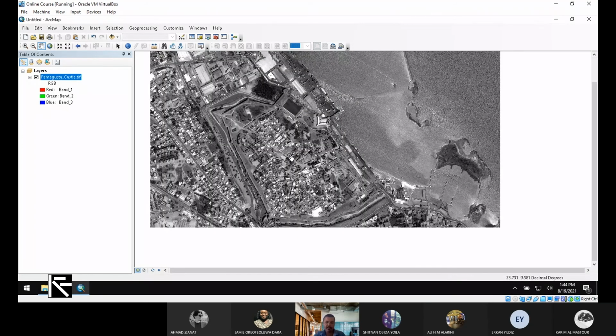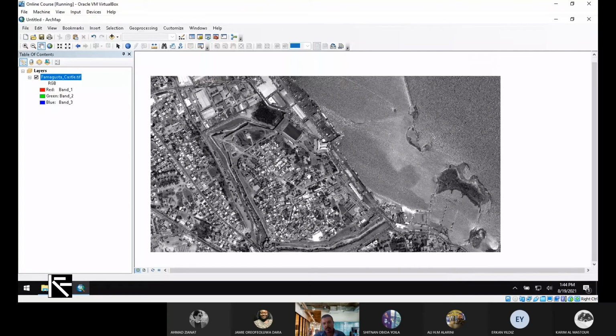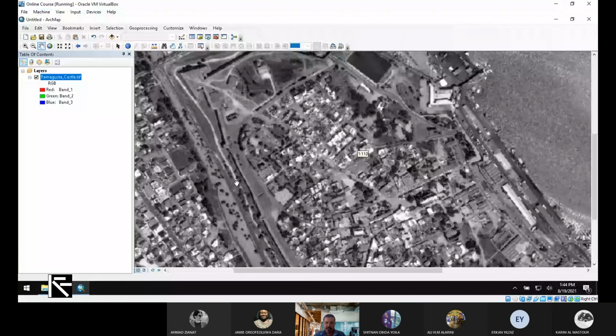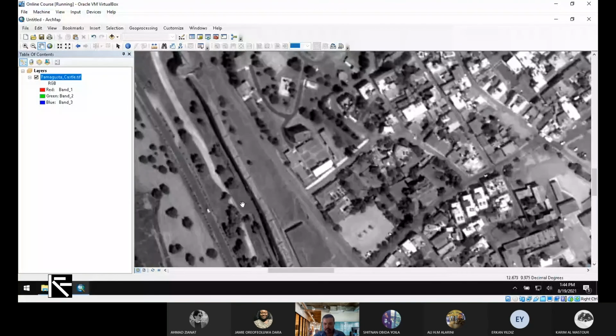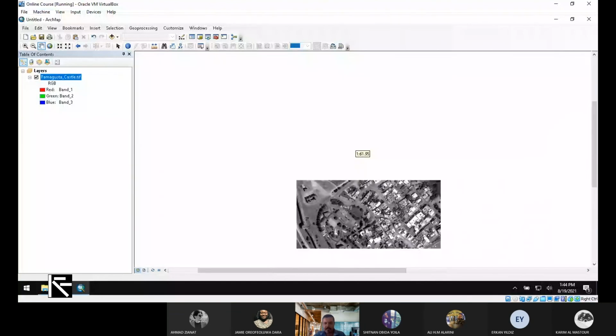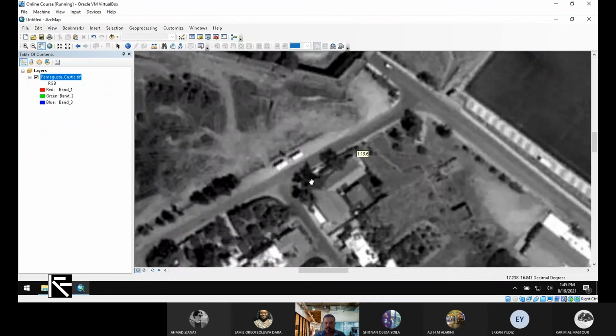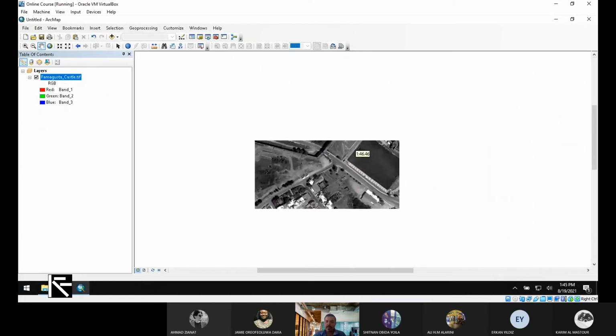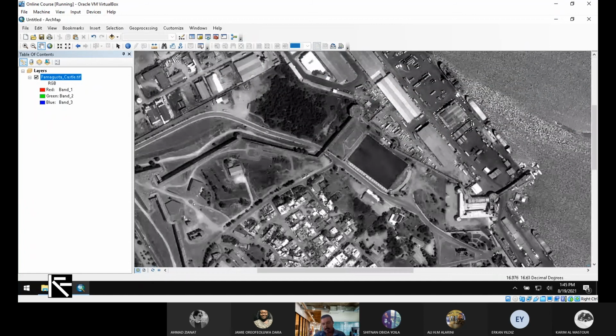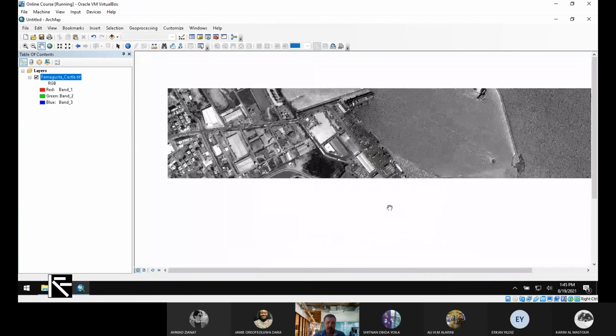Just as an example, maybe you do these things in AutoCAD. You will bring a map into AutoCAD, a scanned map or image, then choose the scale or rescale. For instance, you will say that this street is, I don't know, 6 meters wide. So then draw a line and say, okay, since this is right now 3 centimeters, I multiply accordingly by the scale factor and then make this one 6 meters. Definitely you do it in AutoCAD.